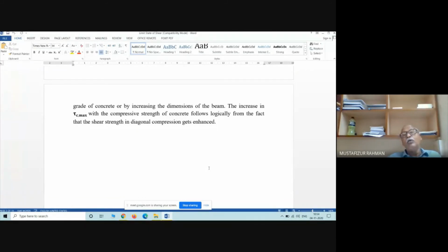Okay. Now, how will shear reinforcement be provided? The shear reinforcement, number one, is the link, the stirrups. Secondly, bent up bars. That means the bar reinforcement we have provided with respect to bending moment. From the bending moment point of view, we do not require all the reinforcement near the support.